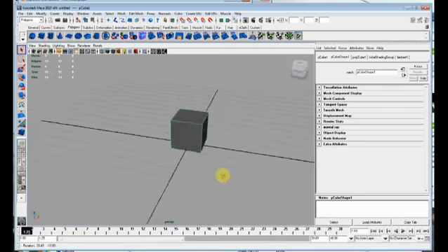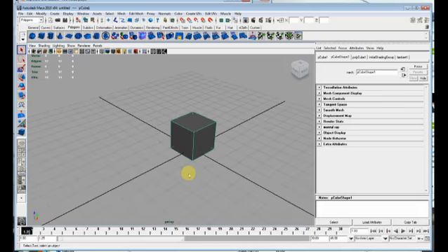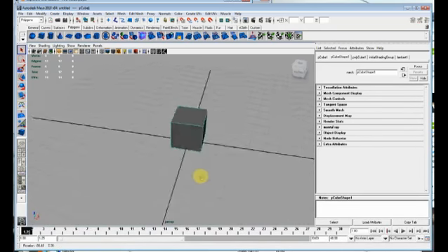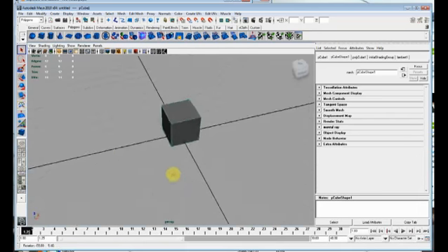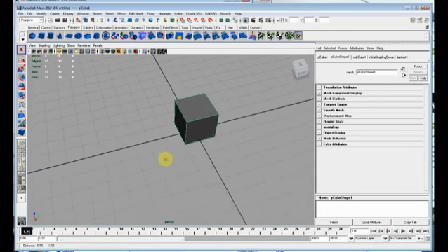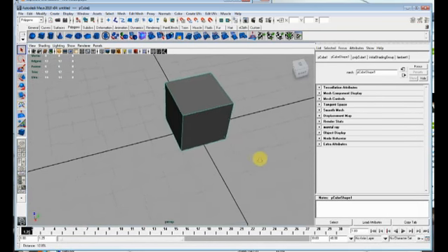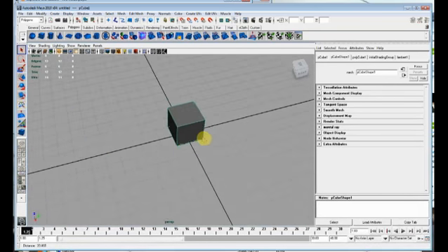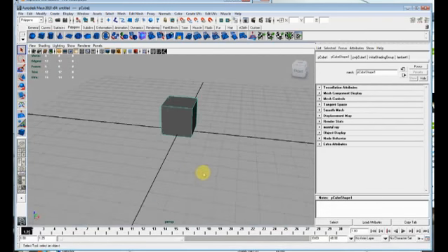Alt left is not giving you rotation. It should. Okay. Alt rotate, Alt middle mouse button, or pushing in the mouse wheel. Alt right mouse button gives you truck. Pan and rotate. Yeah, there's probably a setting in there.